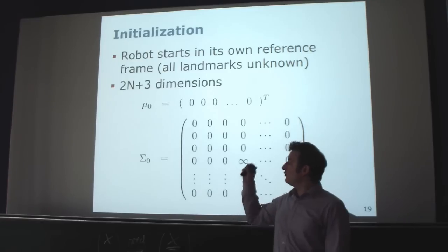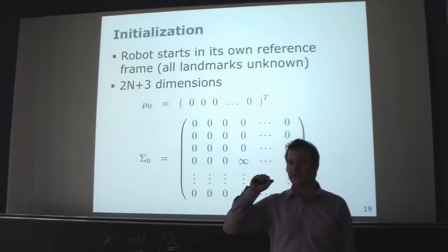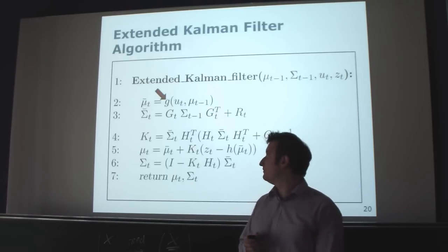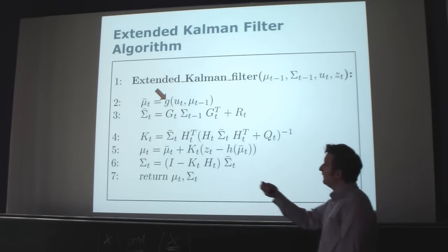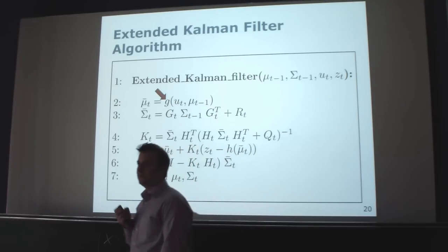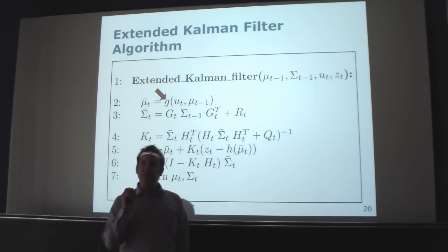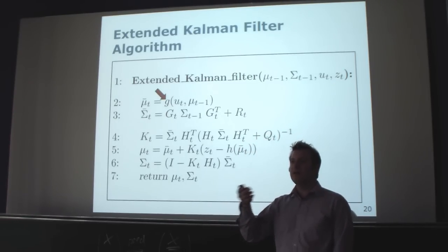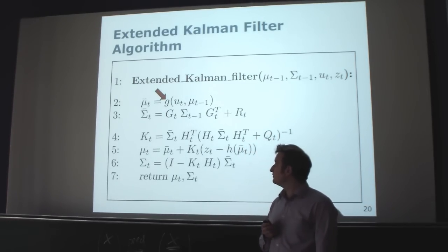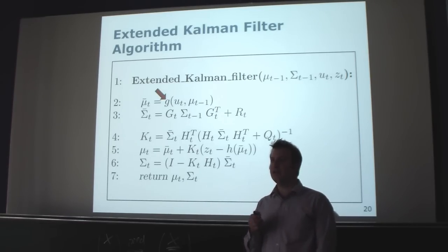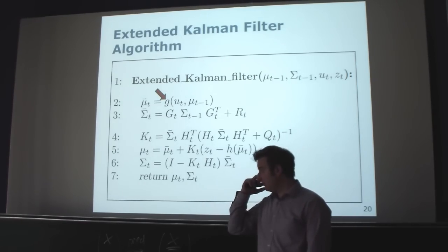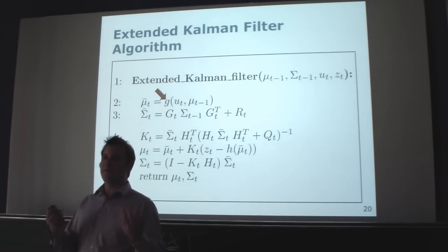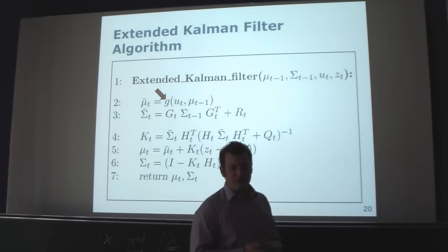Okay. So let's revisit the individual steps of the Kalman filter, and let's go through every individual line of the Kalman filter and see what happens there. The first thing is we have to update the mean. So given my nonlinear function, which describes the motion of the robot in the plane, I want to make a prediction about the new mean. We looked into that last week, briefly explained the motion model for the case of having no wheel encoders, so the velocity-based model for a wheeled system.